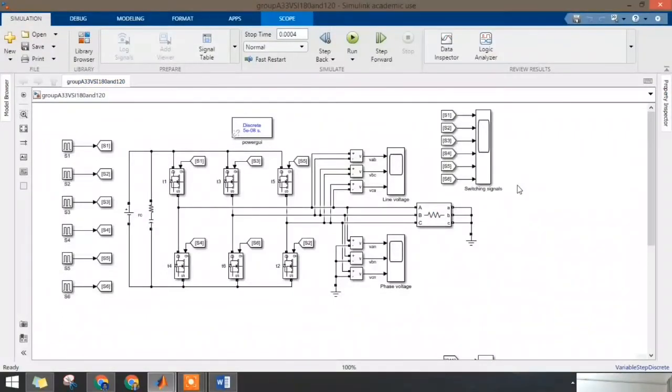As mentioned in the early part, in either the 180 or 120 degree conduction mode voltage source inverter, switches will be active only one in each segment out of three segments. Then there are two sorts of control signals that may be utilized to manipulate the three-phase inverter switches. They are conduction angles of 120 and 180 degrees. In order to obtain the correct output of the three-phase AC signal, each requires various properties.